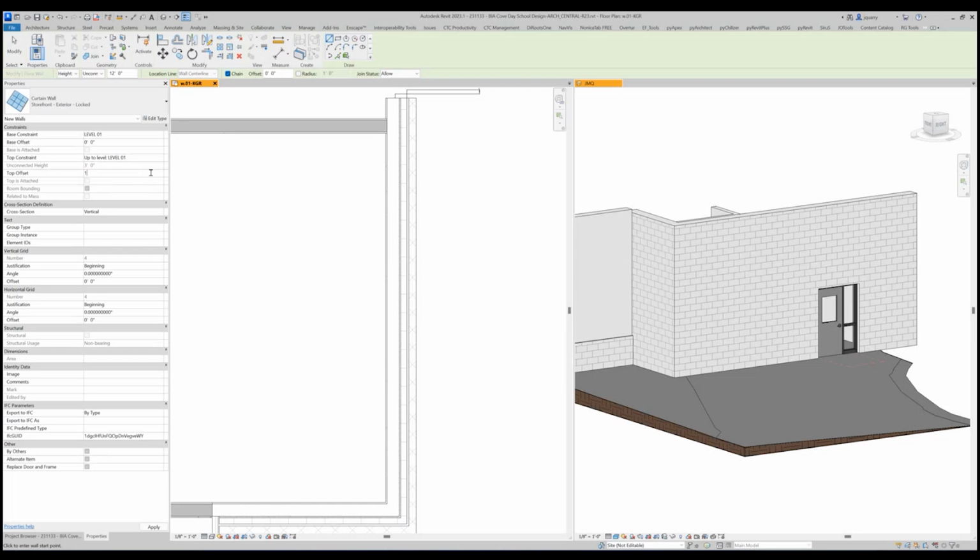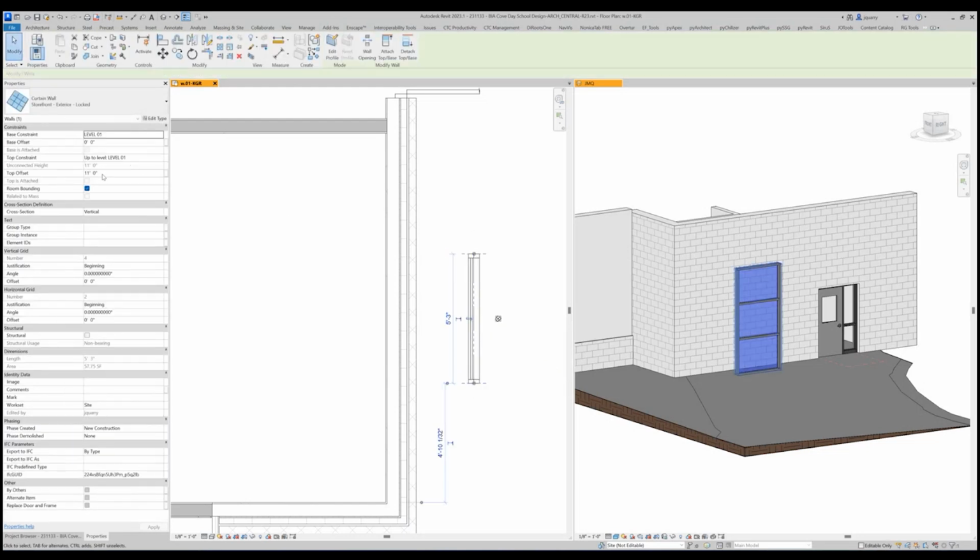So I'm going to create this at 11 feet high. When I draw this, we get an 11 feet high window. That's the top part of the window to match. If you refer back to your frame type A, that matches it in terms of height. Now I could have matched it in terms of width easily too. I could change this to 8'10". I could have drawn it, whatever, right?